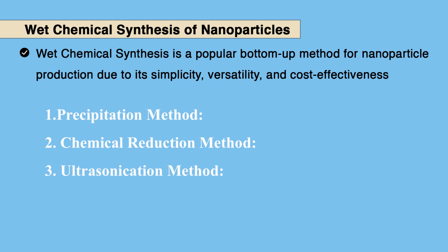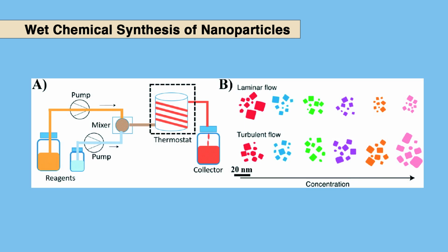The ultrasonic method: high intensity ultrasound facilitates the synthesis of nanomaterials by creating extreme conditions of temperature and pressure within collapsing bubbles in a liquid, that is cavitation. This method is particularly used for synthesizing small spherical nanoparticles of noble metals like gold, silver, platinum and palladium. Ultrasonic synthesis is advantageous because it does not require reducing reagents, offers fast reaction rates and produces small size nanoparticles.